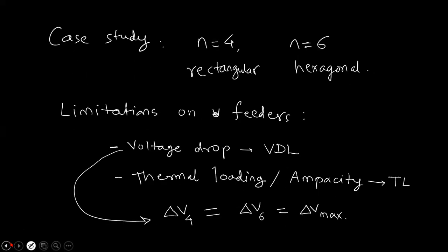Now we can do the same thing when we have a thermally limited feeder, TL feeder. What decides whether the feeder is thermally limited or voltage drop limited? Basically, it depends upon the heat dissipation, what kind of environment the feeders are exposed to.